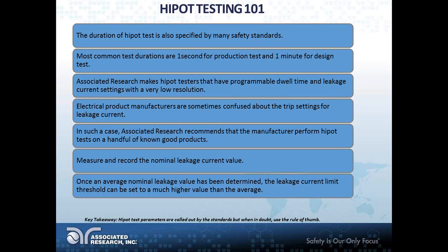Now, this output regulation capability is very important when Hipot testing for 1 second, because it's a very short period of time, and during a 1 second period, the test operator does not have enough time to correct the output voltage if it rises or sags.